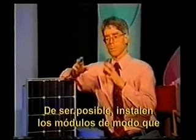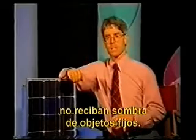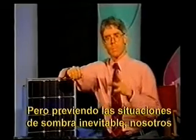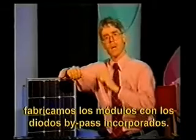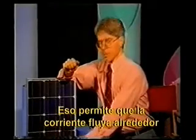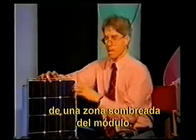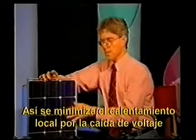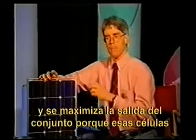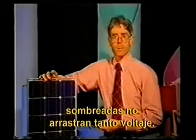If at all possible, install your modules so that they're not shaded by fixed objects. But in the case of shading that we can't avoid, we as a manufacturer build in bypass diodes into every one of our modules. That allows for current to flow around a shaded area on a module, thereby doing 2 things: minimizing local heating because of the voltage drop there, and maximizing array output because we don't have as much voltage being dragged away by those shaded cells.